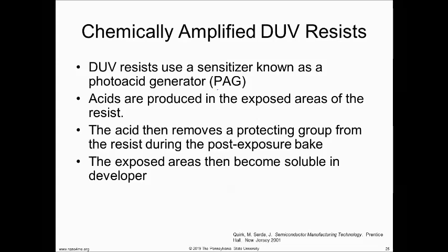stepper. So we're doing contact alignment in this presentation, but I did want you to know about this stepper thing, and I did want you to know about deep UV resists because they're phenomenal in industry because they save money. Like literally, your cell phones would cost a lot more if we didn't have deep UV resist. Does everybody see that? This makes modern manufacturing a lot more cost effective.